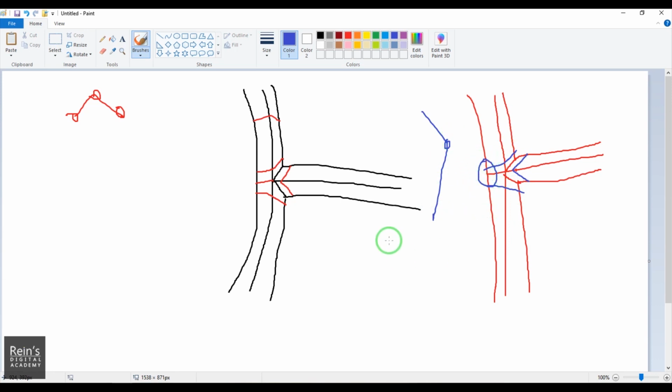If there is an arc like that and there are 3 points at one place, it can give me a corner like that. So to avoid that, you can always take this line away from this point. Keep that spacing here, which is very important. Okay, so keeping these points in mind, I will model.